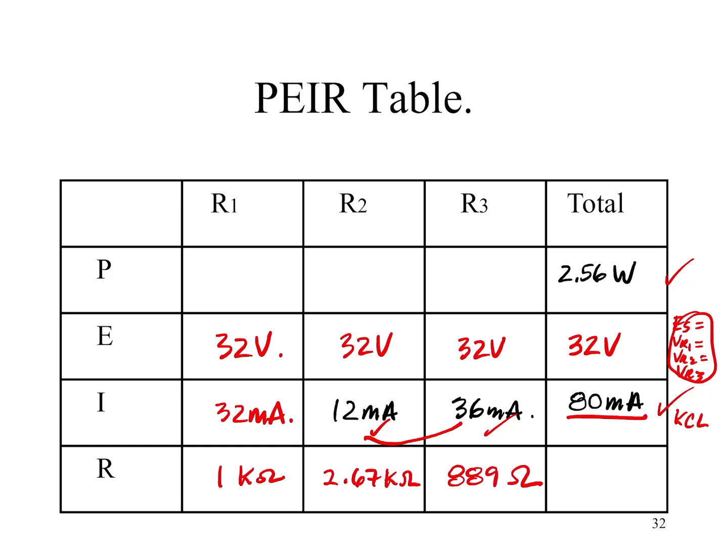And then from there, you can go about a division here to quickly determine your parallel resistance. Now, of course, what you could do is apply the sum of the reciprocals for each one of these, and you would get the same result. So 32 divided by 80 exponent minus 3 is going to give you 400 ohms.